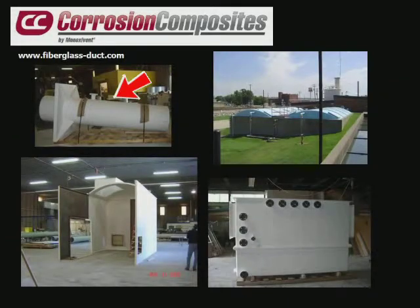On the upper left, you're looking at a stack with an integral curb cover. This is something we like to do instead of going with the conventional curb cover, which involves sheet metal and tar and so on. This is corrosion resistant. It's structural. It can support the stack and the fan above, if there's a fan above it. Something we do often.